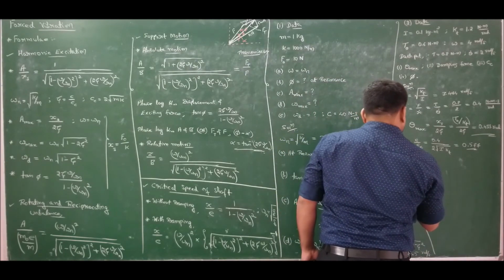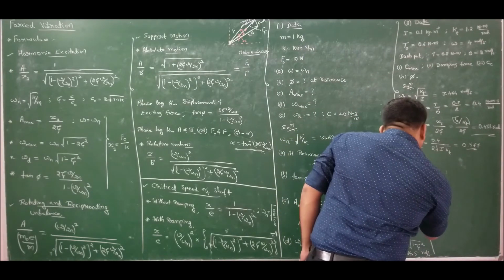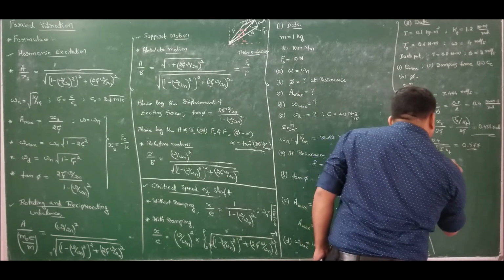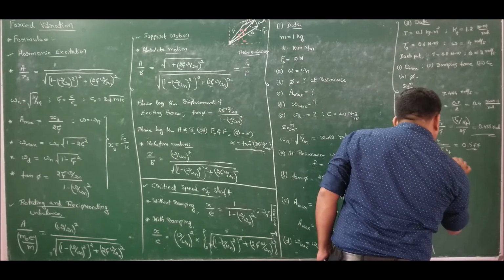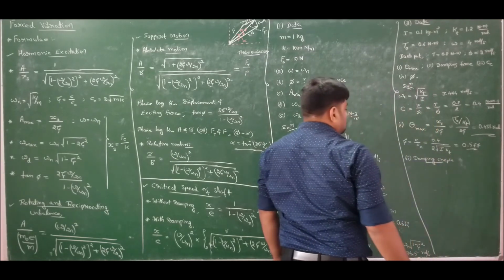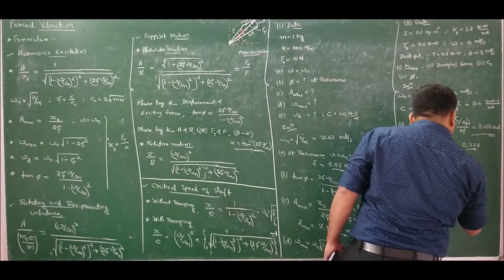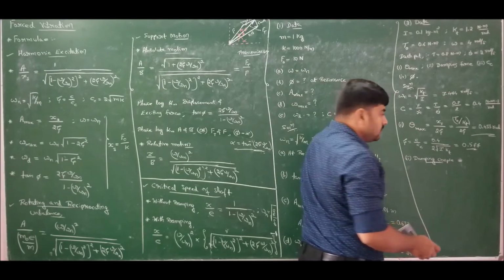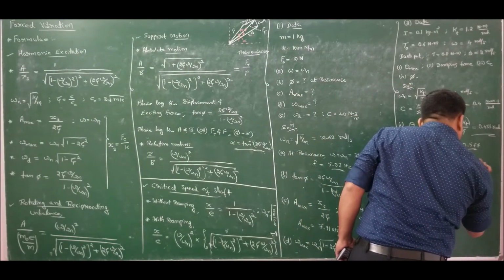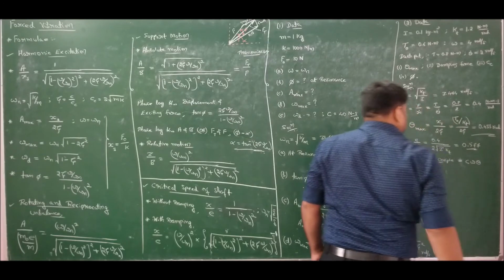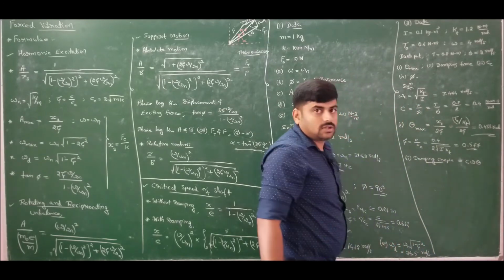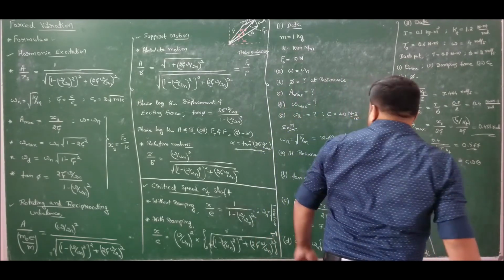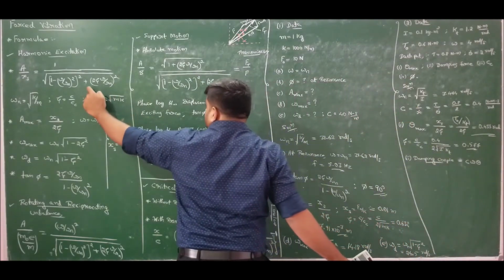Moving to the second one, that is the damping force or couple, because here we are discussing torsional systems. Damping force is C omega A, so damping couple will be C omega theta. Now what is the value of theta? Theta is also unknown. This is theta max, not theta. I want theta, which is nothing but the amplitude, so use this equation and replace A by theta.